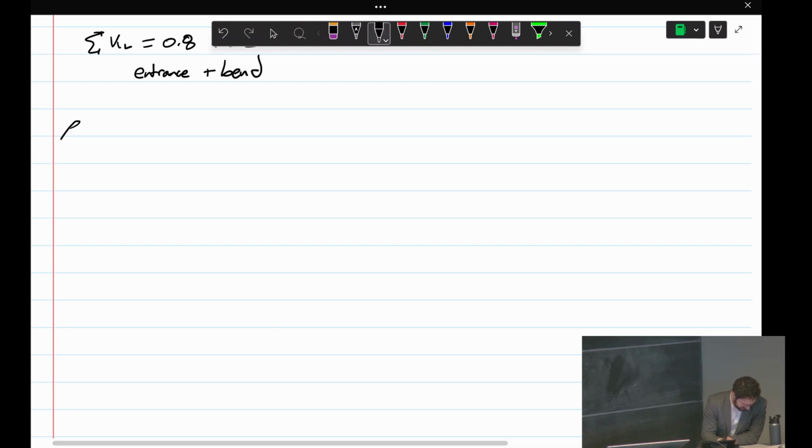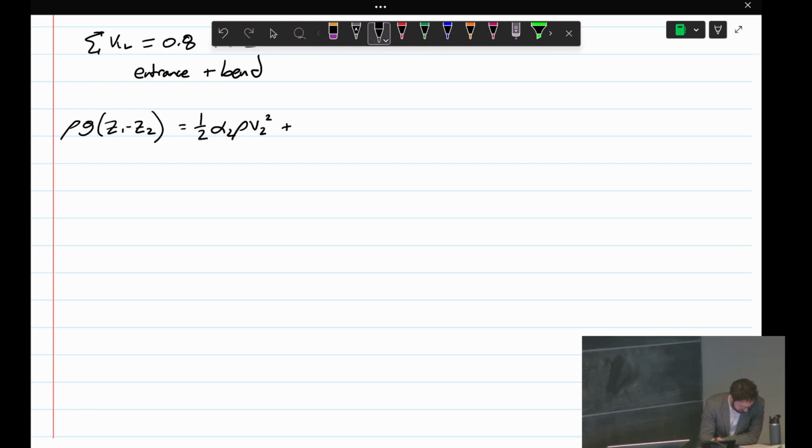So this is the reason that this type of problem is considered a little complicated. Because for the friction factor, if we use the Haaland equation, we can explicitly find the friction factor. So we don't need to iterate. We don't need to sub-iterate.